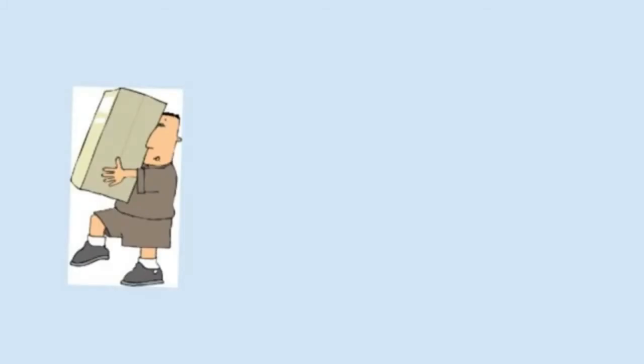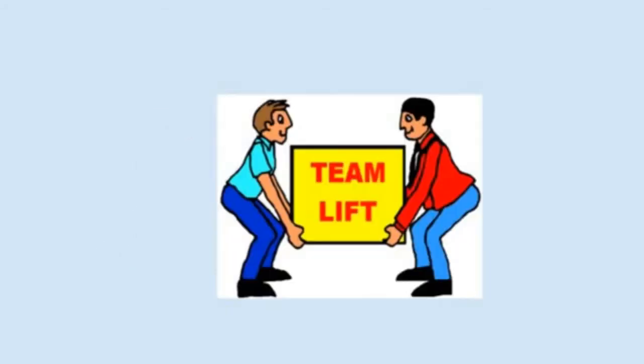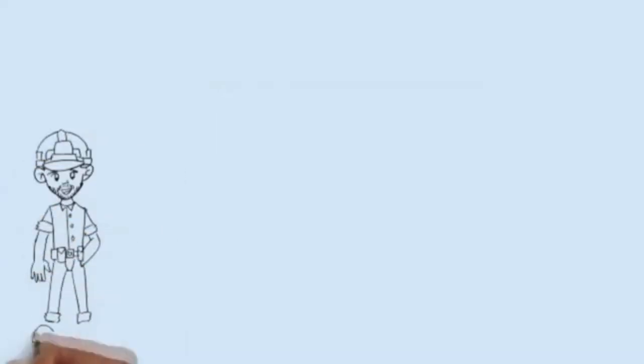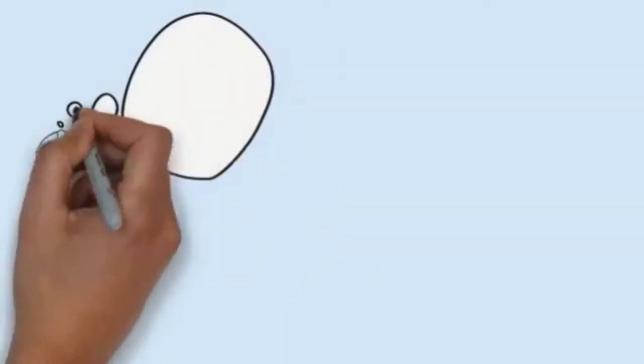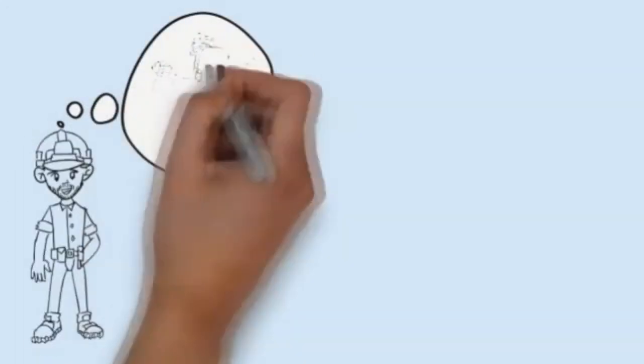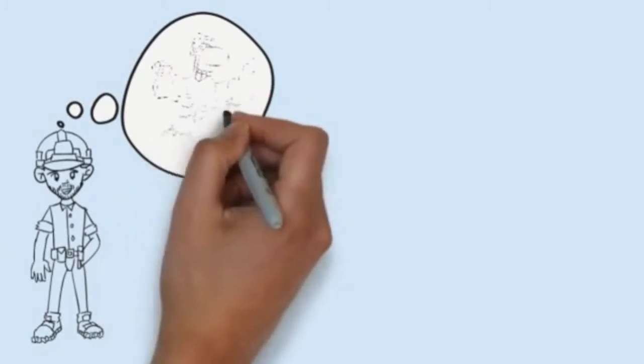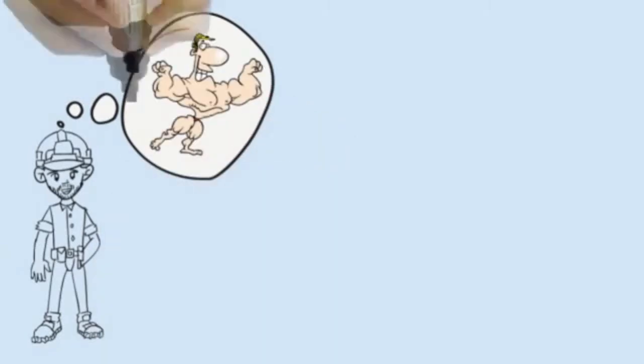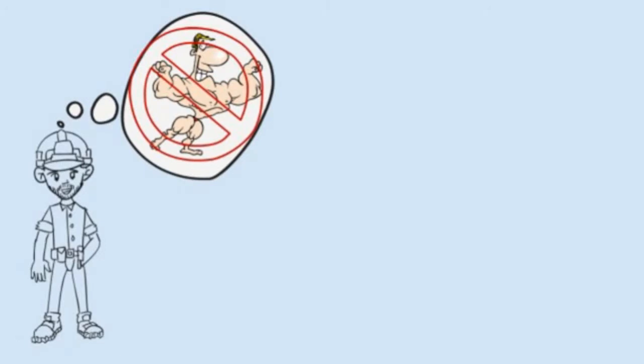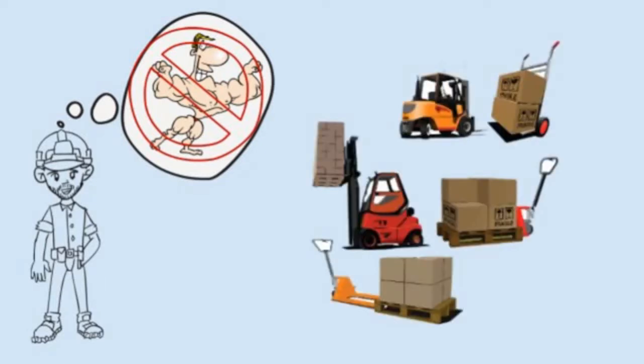2. Can you lift the load manually, or will you need help? Help could be in the form of a second lifter or a step up to some type of a mechanical lift assistive device. You should know your personal limitations. In other words, what amount of weight can you safely lift without risking injury? Even if the load is within your limits, consider using mechanical help whenever possible. But if the item is heavy or ungainly, get help. Don't let your ego get you in trouble. Get a second person, a hand truck, forklift, dolly, or whatever else is available.